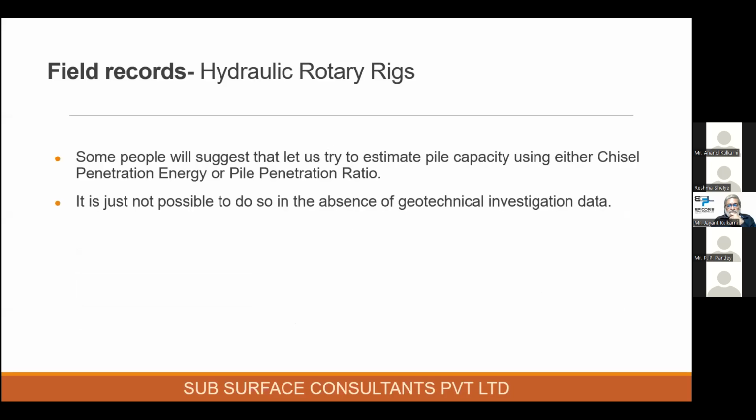Then I'm coming to a very important point here. Some people suggest that let us not do any investigation work, go to site, bring a rig and directly drill a pile there, and find out what is the chisel penetration energy or what is the pile penetration ratio, and based on that allow us to estimate the pile capacity. Now that is something which is just not possible to do, basically in the absence of geotechnical investigation data.